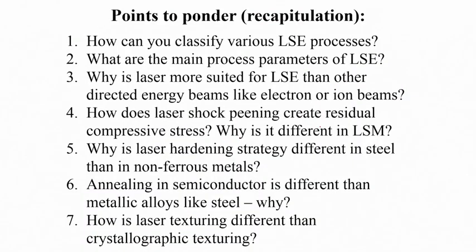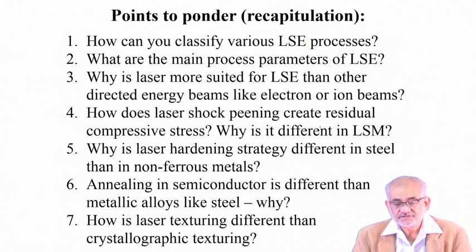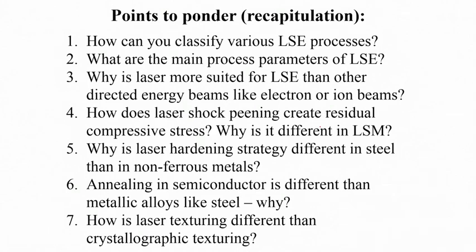So in order to summarize, we can do various kinds of surface engineering using laser surface engineering, where either we change the composition and microstructure both, or we change only the microstructure and not the composition. That is possible very easily because we can control the heating rate, the heating process, and so on.